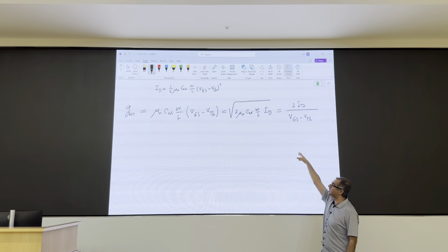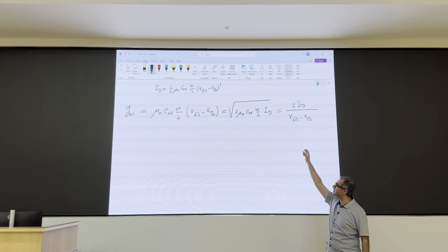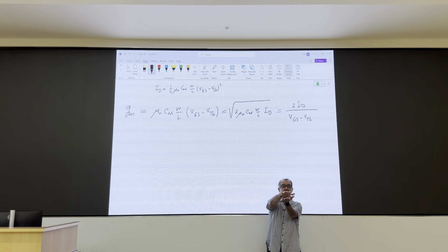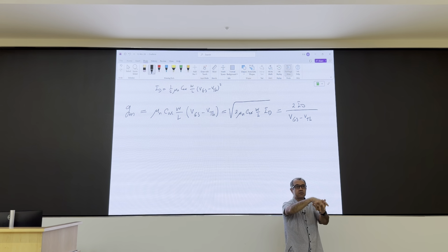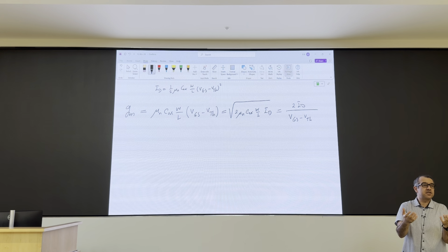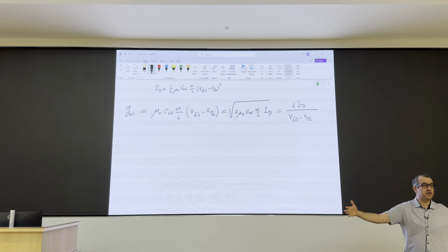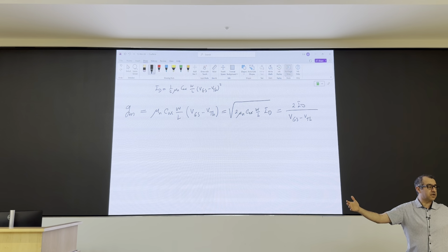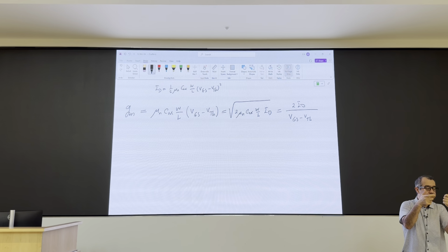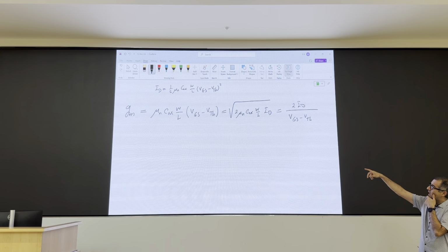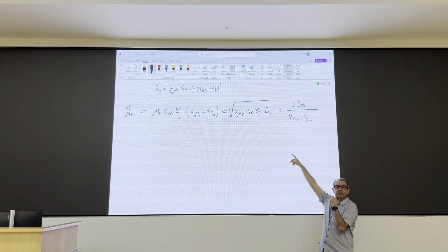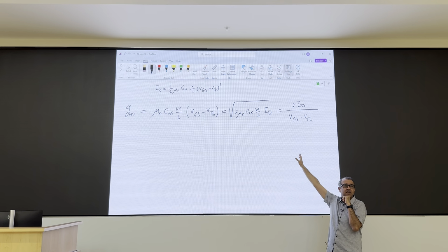addition to your ID that you had before, IC for BJTs. You can also play with the dimension of the device. Same VGS minus VTH. If you want more current, if you want a higher transconductance, you make your device wider. In integrated circuits, you can do that. That's it. Doubling the width is like putting 2 transistors in parallel. So you can do that for a MOSFET. From the second formula, you see a little bit of bad news.